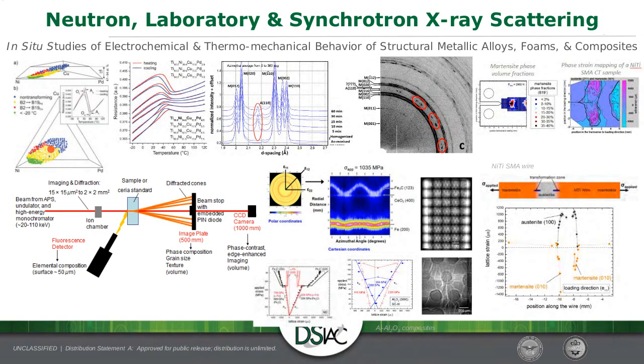And then of course you can tie this to nano indentation and other laboratory techniques to look at things. We can also track with synchrotron. We can track phase formation and its morphology. So how does it form? How does it change over time? In this case, I'm showing an H-phase precipitate that has this star-like cluster. That happens and then it goes away, and then a more stable H-phase comes back in. So we look at that sort of thing.